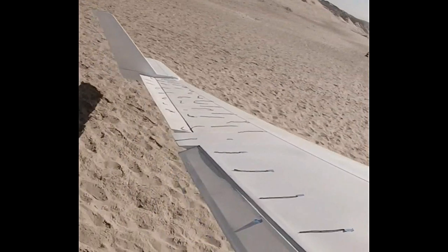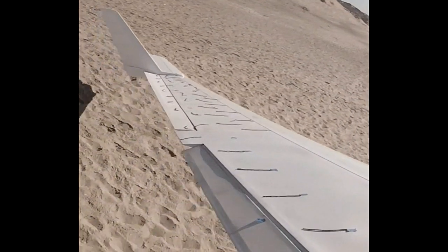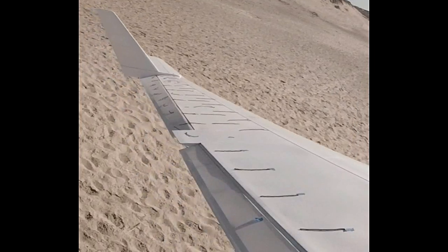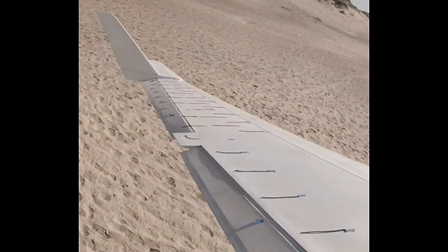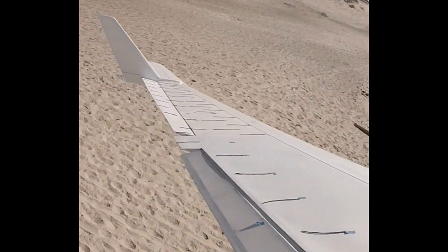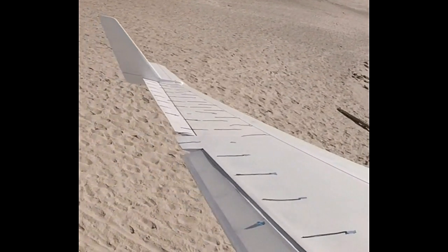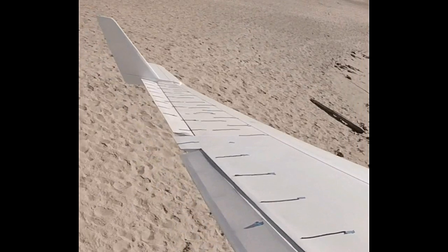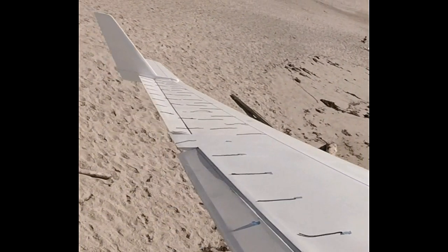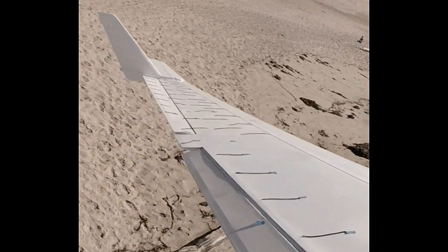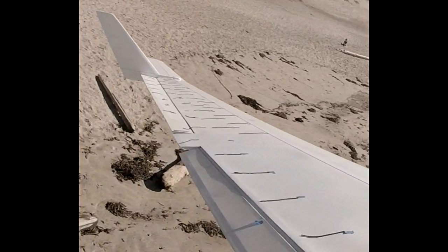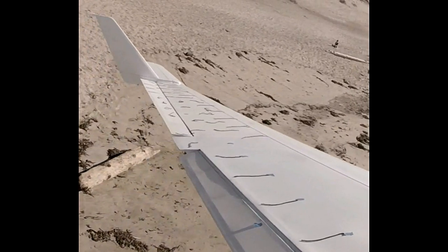And I'm struggling with the pitch right now. There's some stall occurring there, and I hit down elevator to stop that stall. And I don't know if that stall is probably caused by premature separation on the elevon. Whether it's a laminar separation bubble or not, I don't know, but that was the start of a stall. And as I come around here, I attempt to pull in some up elevator to slow it up, but at this point I'm sitting too far forward.